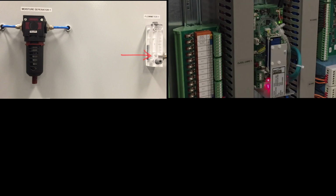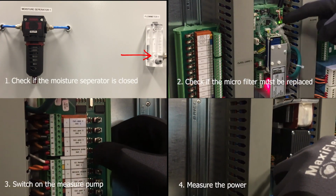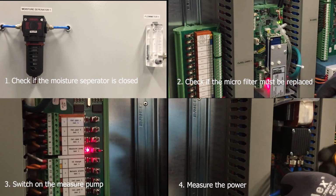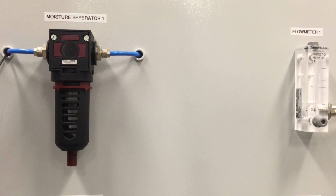If the system indicates a flow alarm on multiple stores, and you have checked whether the problem is in the control cabinet, this can be for several reasons. We will now show you which steps you can take to find out what triggered the multiple flow alarms. The flow meter shows that there is not enough flow to conduct a reliable measurement. The flow should be around 1 liter per minute.